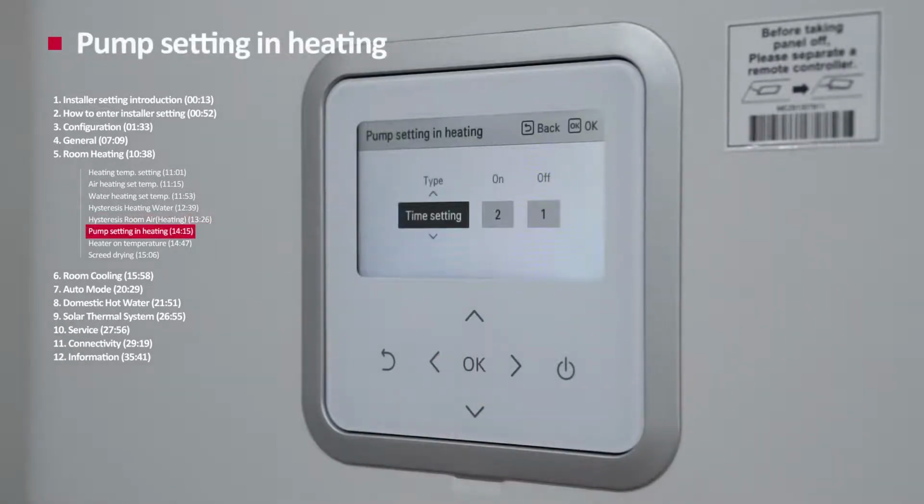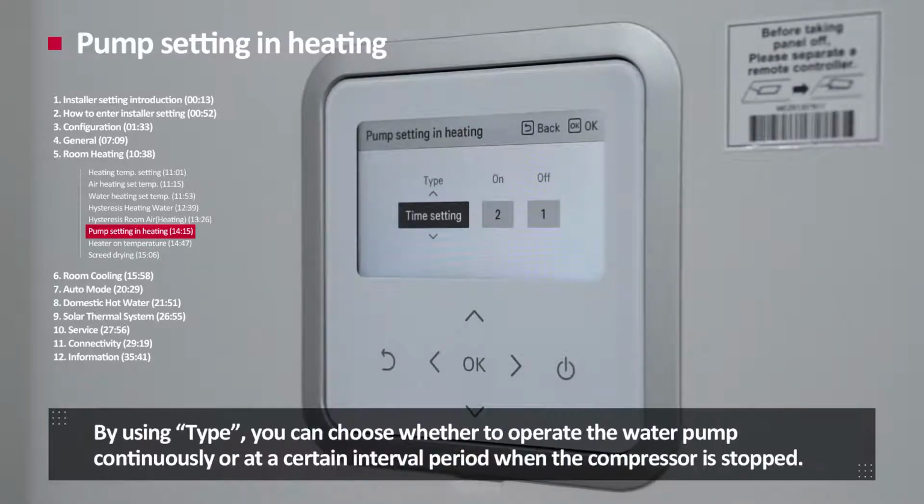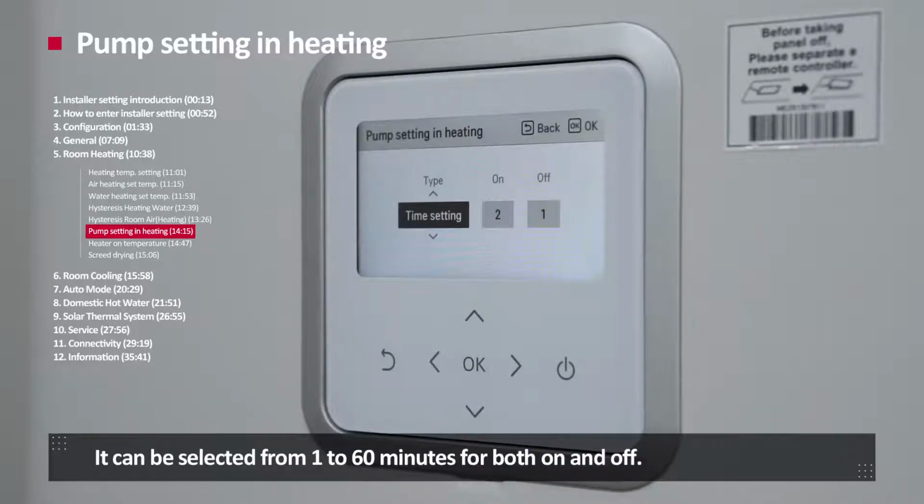Pump setting in heating. It is to determine how to operate the water pump when the compressor is stopped in heating mode. By using type, you can choose whether to operate the water pump continuously or at a certain interval period when the compressor is stopped. On means the duration of pump running time, and off means the duration of pump stop time. It can be selected from 1 to 60 minutes for both on and off.